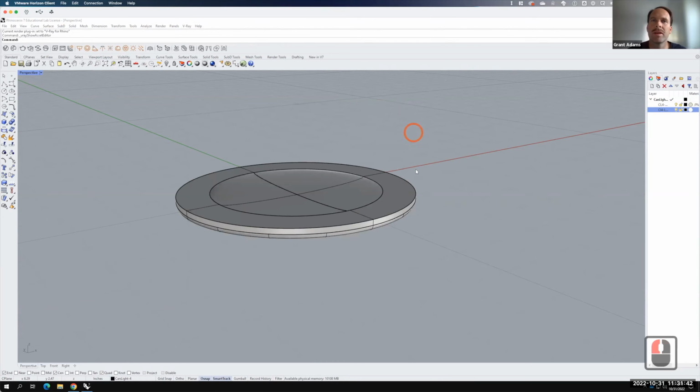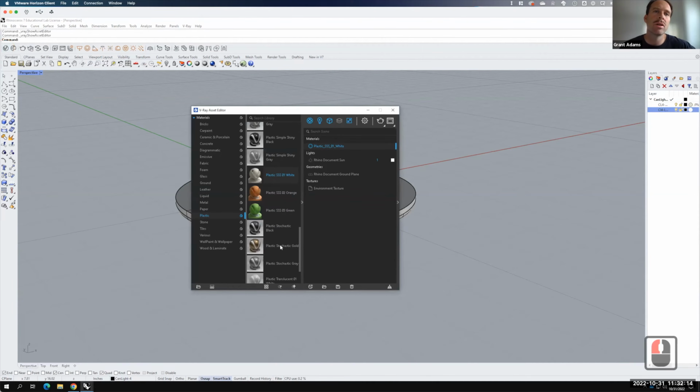But the last piece of the puzzle, and you can see this, is that when we look at a light fixture and there's a lens on it, in this case, the can light, and so if you were to look up at your ceiling at a can light, for example, you would discover that when it's on, you'd see the lens kind of somewhat illuminated, kind of glowing. And so we need to create a material that represents that glowing material. And in V-Ray, that material is called an emissive material. And so we're actually going to create that emissive material from scratch.